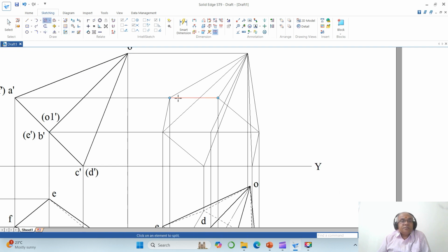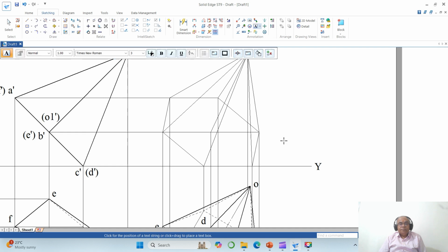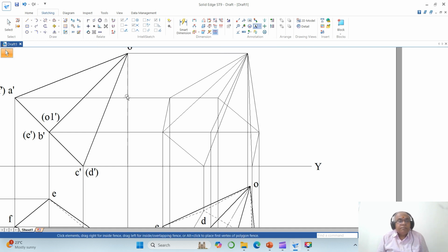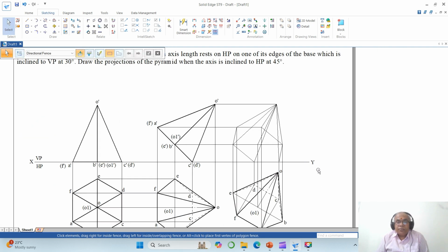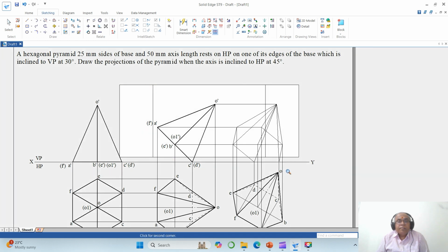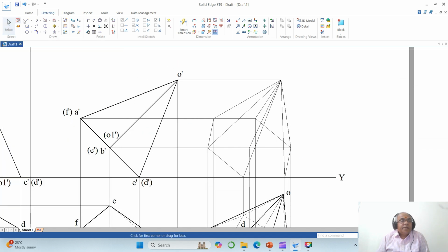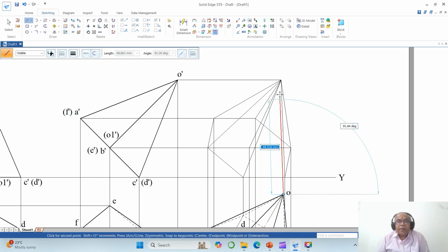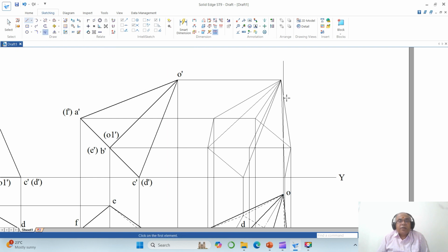Now you go to split this, okay, split this line till here, okay, then use, okay, fine, all these points have been split. Now you go to text here, sorry, this is a mistake here, okay. So I'll go to the line command, draw a line from end point to this, okay. Now we have a trim corner between these two, okay.